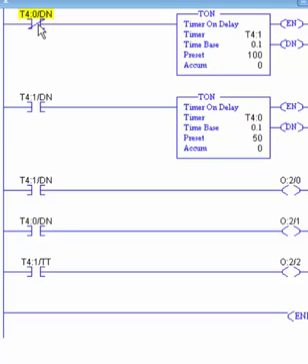That's going to make this false, because here I'm saying, are you not done? When this is false, you may have discovered that as soon as this goes false, the accumulator gets reset, the done bit shuts off. As soon as that done bit shuts off, that's going to make this false. That's going to turn this accumulator back to 0, shut this done bit off. When this done bit turns off, this will be true again, and the cycle repeats. And this will count up to 100, turn this one on, this one counts up to 50, turns this one on, shuts this off, resets this, resets this, turns the done not on, starts this thing all over again.